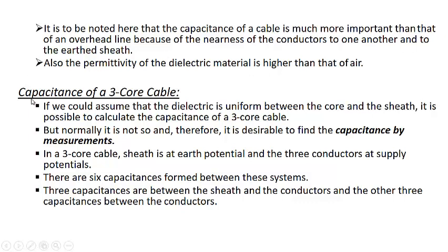Now, similarly, we can calculate the capacitance of a three-core cable. If we assume that the dielectric is uniform between the core and the sheath, core means conductor, it is possible to calculate the capacitance of a three-core cable, but normally it is not so. Therefore, it is desirable to find the capacitance by measurements, and we always try to do this. We calculate the capacitance by doing some measurements.